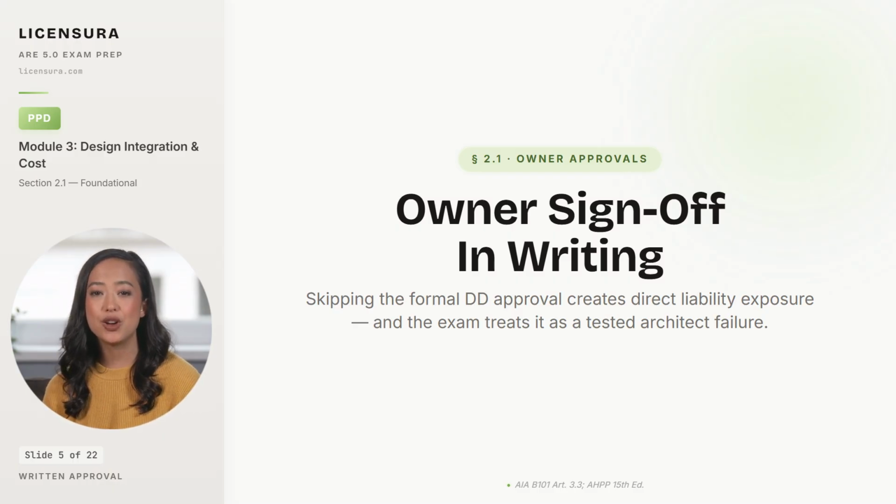It is the moment that you and the owner agree on scope, quality, and budget alignment for what is about to get drafted as construction documents. Skip it, and you are personally exposed when the owner later claims the building you drew was not the building they approved. The exam tests this directly.